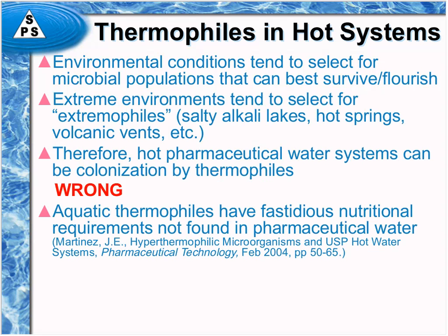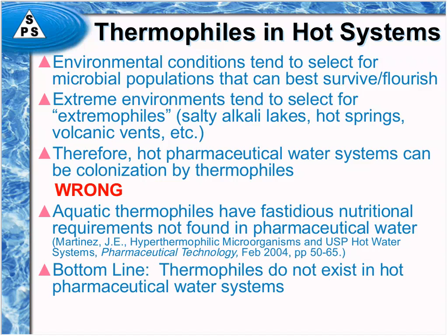There's a reference listed right there by Martinez that talks about every single known hyperthermophile and what its nutritional requirements are, and not one of them could have a chance of living in a pharmaceutical water system. So the bottom line is that thermophiles do not exist in hot pharmaceutical water systems.